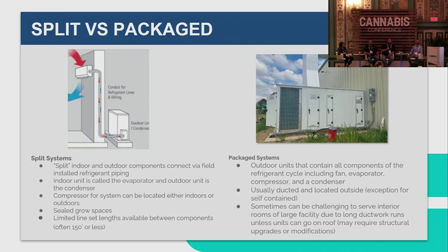At that point, really the operation and how long your unit's going to last, mainly oil return getting back to the compressor, is going to be largely determined by how good your contractor is at following instructions and piping up refrigerant piping. There's a lot of great ones out there. There's some that aren't so good. If you have a split system and you're constantly losing compressors, not lasting more than a year, something to consider, even if you're an existing owner-operator and losing them, is look at that refrigerant piping if you do have a split system.